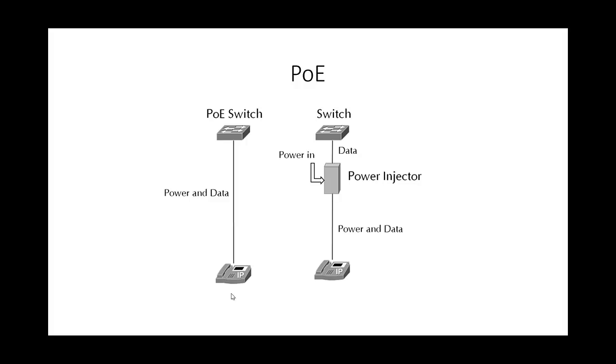Nowadays, the LAN infrastructure is being used more and more to deliver telephony to the desktop through VoIP, or Voice over IP, using IP phones that are connected to switches by UTP Ethernet cables. A conventional telephone derives electrical power that it needs from the telecommunication provider's telephone network. In the case of IP telephony, this power is provided through the Ethernet cable using a technique called Power over Ethernet, or PoE.